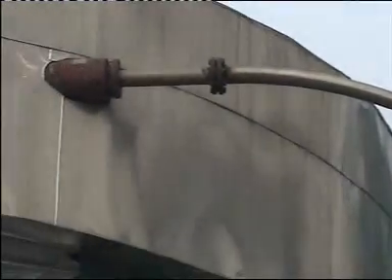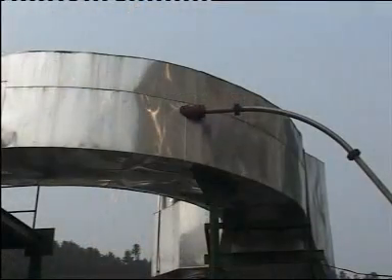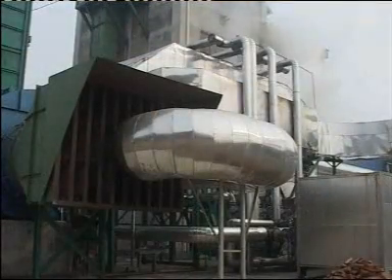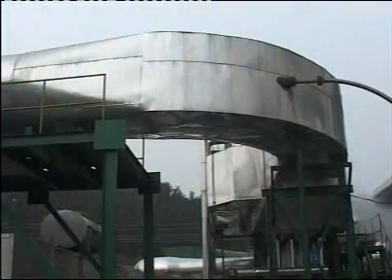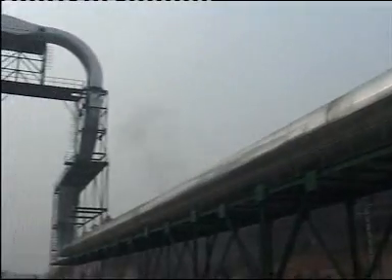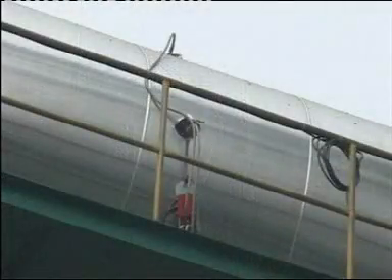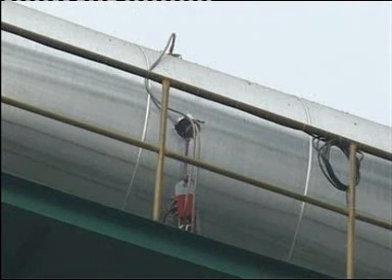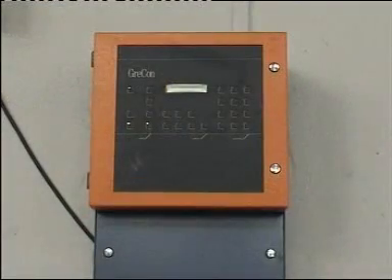After glue spraying and waterproof treatment, the wet fiber is blown into drying duct of the dryer. The wet fiber is mixed with hot air current, and the fiber is suspended in such hot air and effectively dried at the same time. In order to prevent fire, spark detector and fire extinguishing device is set on the drying duct.